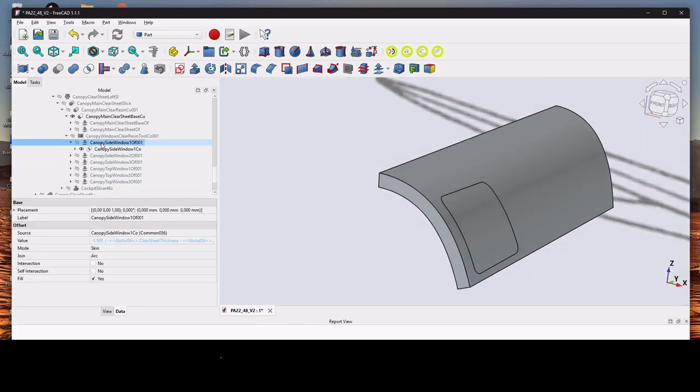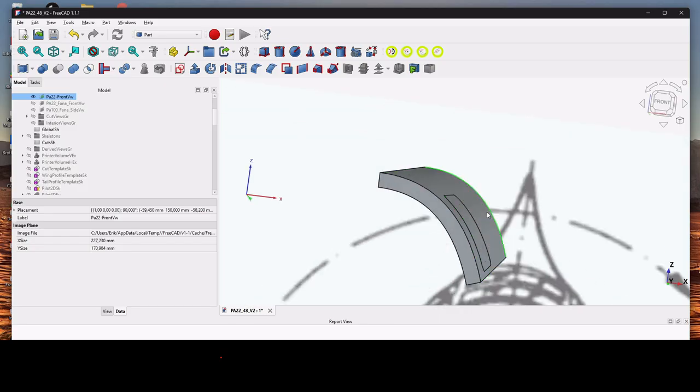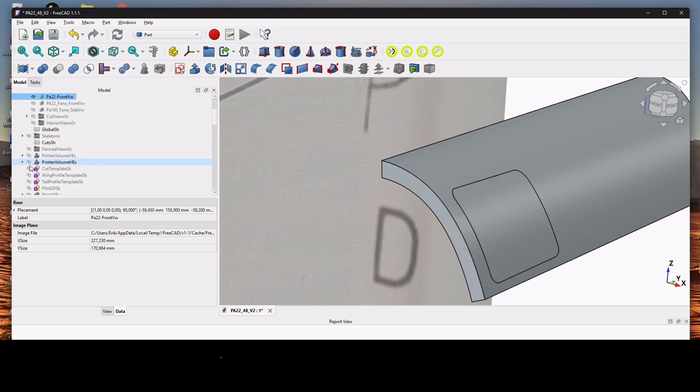And in terms of width, I'm going 0.5. So that means you have to do a little bit of arithmetic here. If the thickness of the thermoform is 0.3 and I'm going 0.5 deep, that means that inside there will be holes of 0.2 mm.